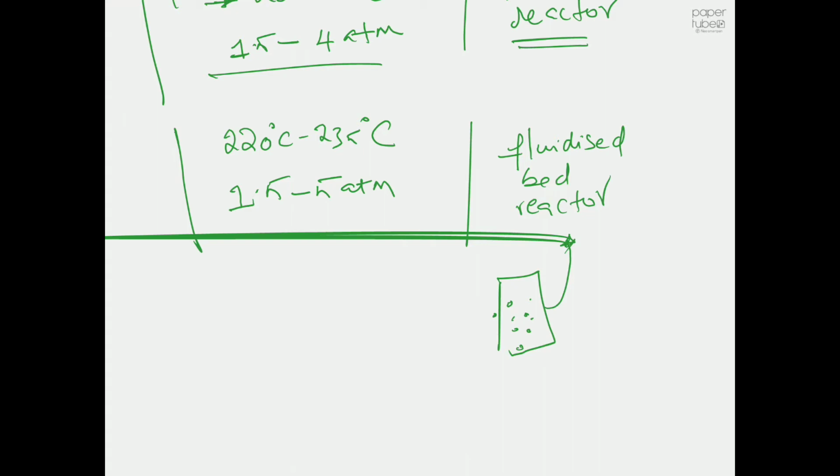But in this exercise I'm going to stick to the fixed bed reactor, and we are going to design a fixed bed reactor, something like a plug flow reactor, which is very easy to implement in Aspen HYSYS. And we are going to model this plug flow reactor as a catalytic reactor, so it will contain some catalyst.